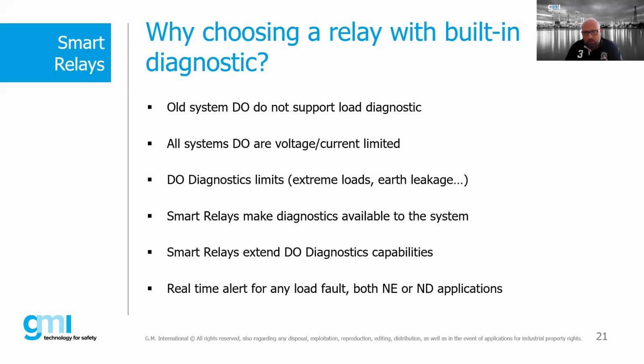If we consider loads such as valves, sounders, speakers, they usually need more than 500 milliamps at 24 volts, which is usually what the digital output card can provide. In this case, the introduction of a safety relay in the loop allows us to drive the load and extend also the diagnostic capability of the system.